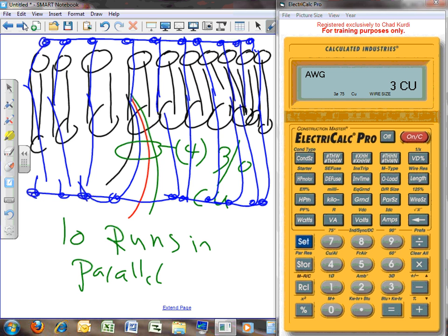And on the top and on the bottom, 500 feet away, you have the same set of lugs, 10 of them, so you can land all the cables on both sides. You guys, are you with me? Imagine 10 of these, one side, each side has its own lugs, and all tied at the end. That's what parallel conductors are.